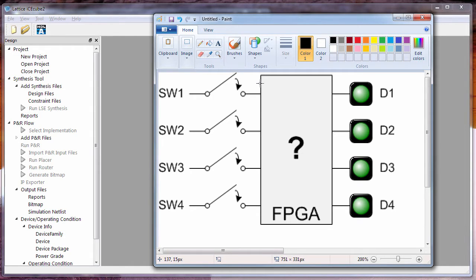So I'm going to be taking you through both the Verilog and the VHDL solutions and going through the entire flow of the build process. Now this flow is important to get down and to pay very close attention to exactly how this works, because it's a multi-stepped approach and it's not very intuitive. So I'll go through this once for this video, and for future videos I will expect that you will just know how to build the FPGA image, and then also how to program it to the Go board. So this is definitely an important video. Like I said, the code itself is not very complicated, but it will exercise some basic functionality and take you through the process. So with that said, I'm going to get started with the Verilog coding section.